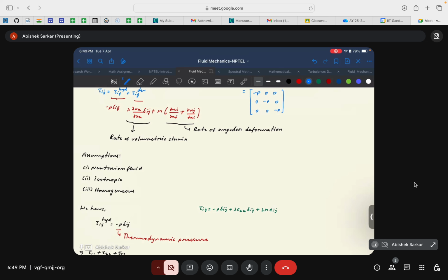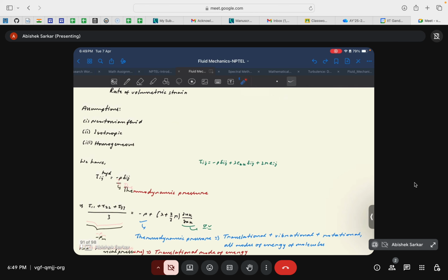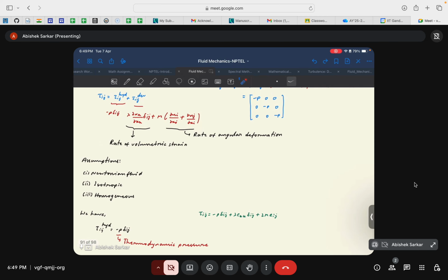So now, as I mentioned, we need to discuss how to handle, I won't say remove, this second viscosity term in the Navier-Stokes equation. So what we will do is, from this equation, let us now consider only the normal stress components. You will see why we are doing it, because there's a very nice relation between the normal stress components and the pressure under certain circumstances.